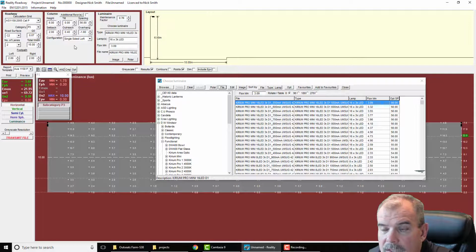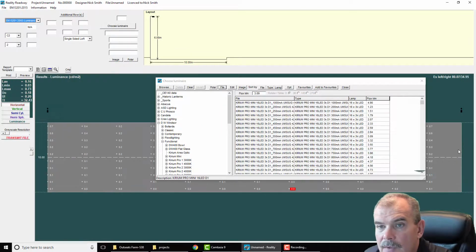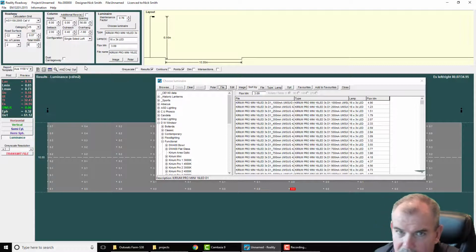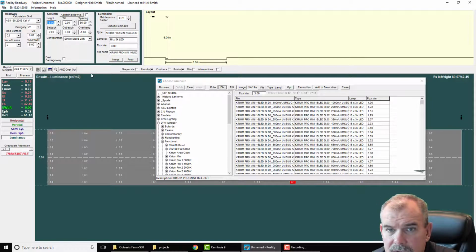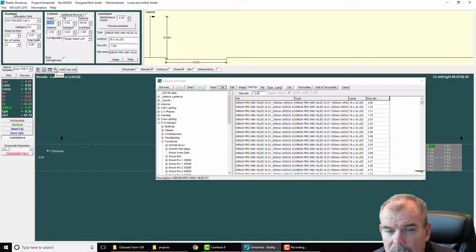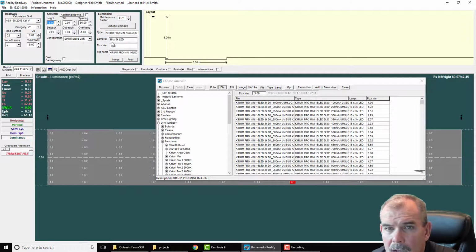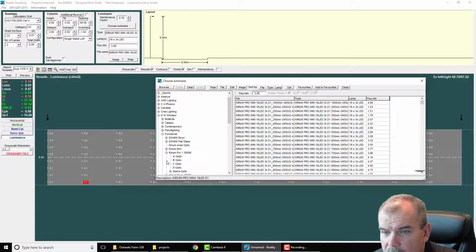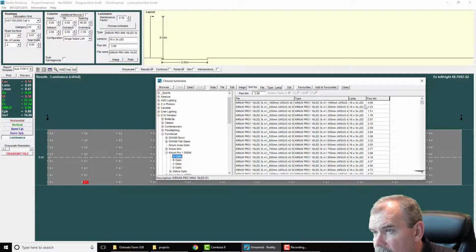So that's the first option, which is to use the Cat P. In terms of Cat V, we obviously calculate luminance. The process is the same: you select the grid, select the category you want to light to, and select the total width. In this case I'm going to put in 8 meters, and the number of lanes. If you want to zoom out and look at where the observer is, we can do that as well. Then set up the parameters. Let's go with an 8 meter column, still 2 meters back. I'm going to use a bigger fitting this time, so let's go with an A optic.